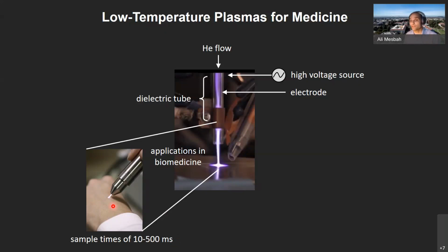Meaning that this is a safety critical application, obviously. Guaranteeing and ensuring the safety of the patient is of utmost importance in such an application. It is also challenging in the sense that, look at the sampling times we're looking at: 10 to tens of millisecond sampling time, meaning that your control algorithms should be really fast and efficient computationally to be able to deploy them in real time.